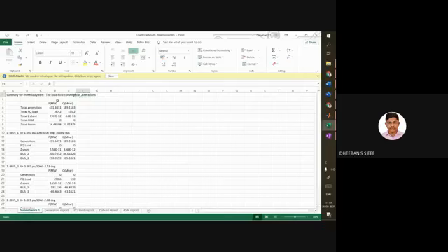And here you can see, your bus 1 is the swing bus, or the slack bus. The slack bus's other name is swing bus, as I have already told. The swing bus won't have any PQ load, so here your PQ load will be 0.